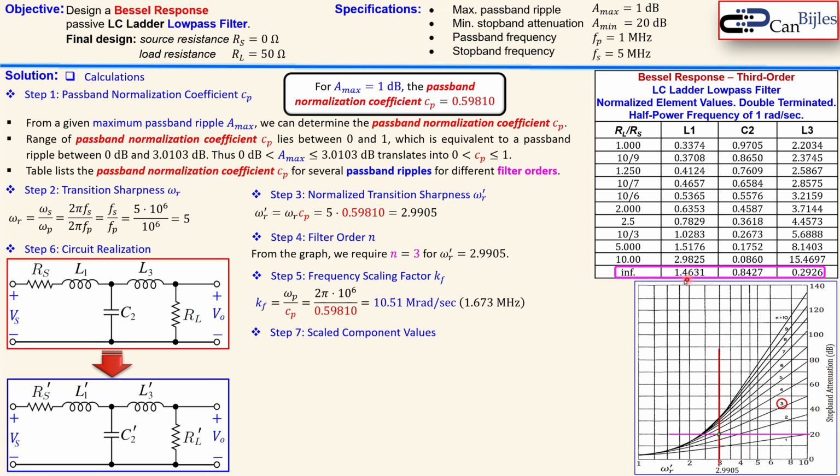So those 3 values are normalized values we need to use to go to the prime values, which are the denormalized values. And we need to use this frequency scaling factor we have found in step 5, and we know that is what the normalization always does. We start from the 1 ohm here. That is always what's done. And we need to go to the 50. That means we need to upscale this in the magnitude by 50. That's why you see here the km of 50 ohm. Okay, we need to use these 2 parameters to go to the primes here.